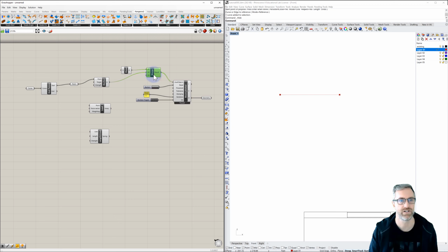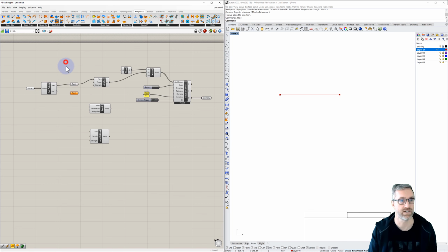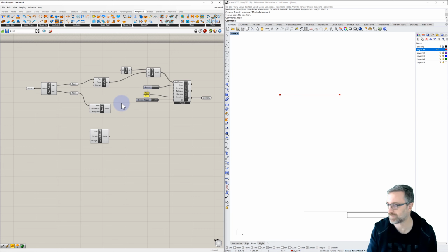And now the next thing is the loads. So we'll create another point container, and we'll feed the endpoint to this. And let's put that point into our load. So basically, we have this simple line. We're fixing one of the points, and we're loading the other point. So what do you expect to happen when we do this?